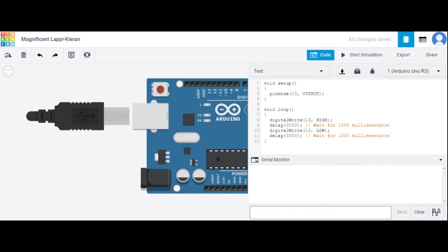This is called serial communication, a universal asynchronous receiver transmitter, UART, on a microcontroller. This microcontroller uses 5 volts for logic 1 and 0 volts for logic 0. Every message you send using UART, universal asynchronous receiver transmission mode, is 8 bits of data or 1 byte.